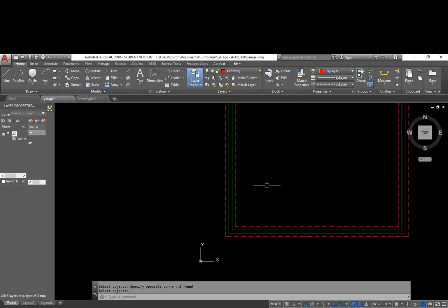So what we want to do is make sure that we use our modular spacing rules or modular dimension rules for concrete blocks. And with each concrete block being 16 inches long and also being able to get 8-inch long ones, half blocks, basically what we end up with is 1'4", 2'0", 2'8", 3'4", 4 feet, 4 feet 8.